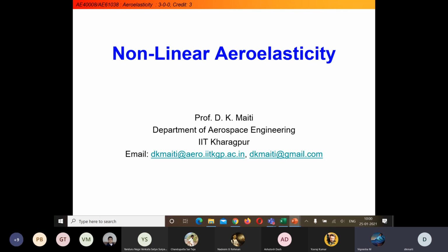Actually, in aeroelasticity, as we have to calculate for different altitudes also, usually we calculate in terms of the dynamic pressure. Depending on the altitude at which it is flying, you will have different velocity, because with altitude your air density will change.